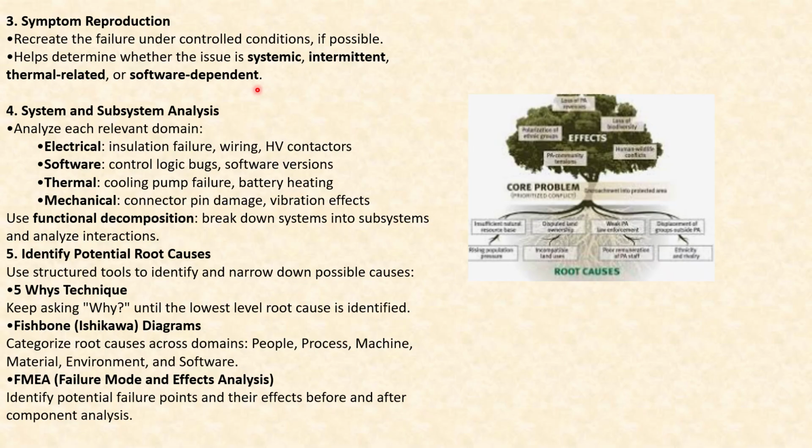Now, talking about the system and subsystem analysis, analyze each relevant domain: electrical, insulation failure, wiring, HV contactors; software, control logic bugs, software versions; thermal, cooling pump failure, battery heating; mechanical, connector pin damage, vibration effects. These are the various domains you have to keep an eye on. And using functional decomposition, break down systems into subsystems and analyze interactions.